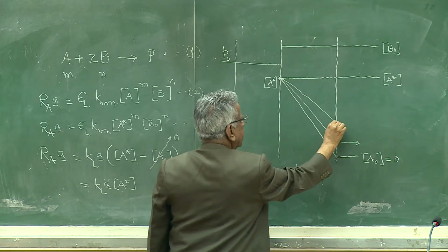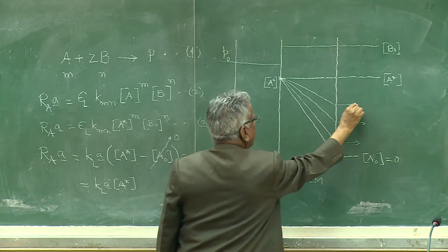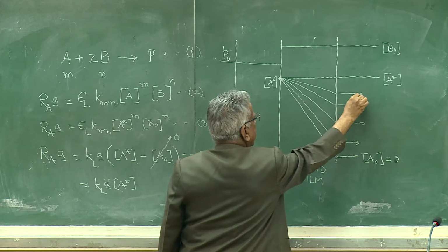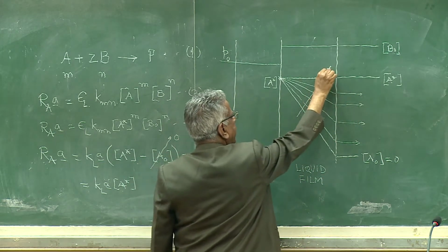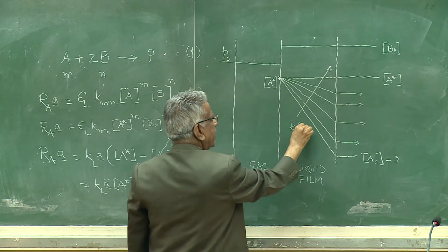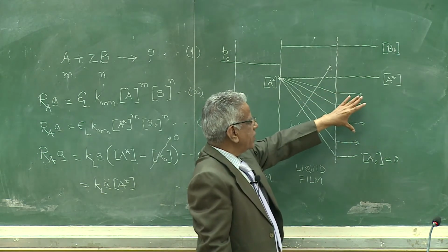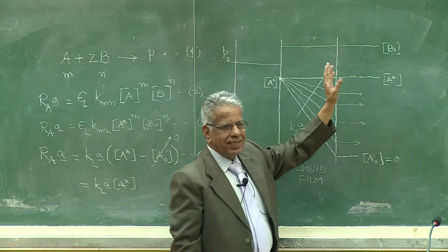Keep on increasing the speed, keep on increasing the dissolution rate, and finally, eventually if you increase the speed or increase KLA, eventually the solute concentration in liquid phase will reach saturation concentration.